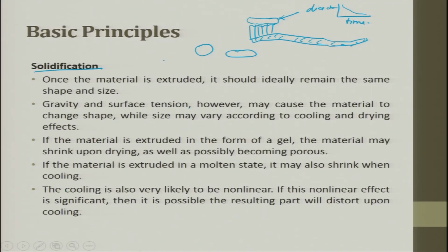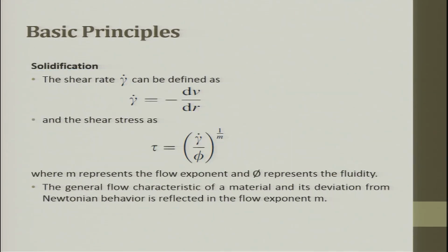On top of it, shrinkage on cooling is also there. The cooling is also very likely to be non-linear. If the non-linear effect is significant, then it is possible the resulting part will distort upon cooling. So, you should keep this in mind when we do the process.